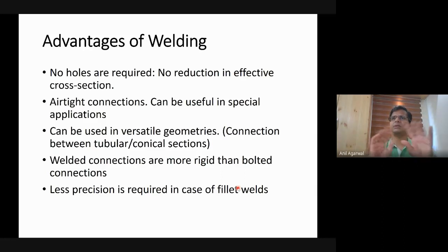Then there may be some welds which are used for holding other things, or connecting other components. You may require welds to connect the ring on the top. Also, there is a ring at the bottom. Those rings have to be welded to the plates, but those are not really making sure there is no leakage in the cylinder. The leakage is prevented by the weld in the middle. So all these big containers that are used for LPG, CNG, whatever, they all have to be welded.